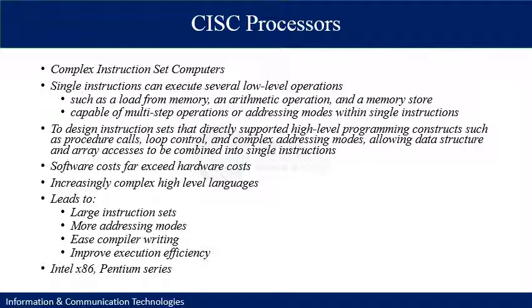So there is also a need to incorporate increasingly complex high-level languages. Therefore, it leads to a large instruction set, more addressing modes, ease of compiler writing, and improvement in execution efficiency. Therefore, CISC complex instruction set computers were quite prevalent to counter these needs. Intel 86 processors and the Pentium series are examples of this kind of architecture.